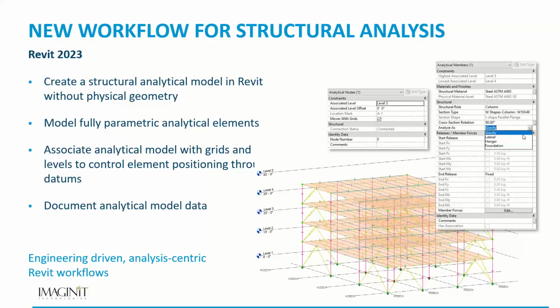So things that you're already familiar with, we can do more efficiently within Revit without actually having any modeled elements at that point. The only thing that we will be fully parametric with is things like grids, levels, and so we can change or control the positioning using those datums as we're doing that. So this is going to allow us to get this stuff moving much more quickly.